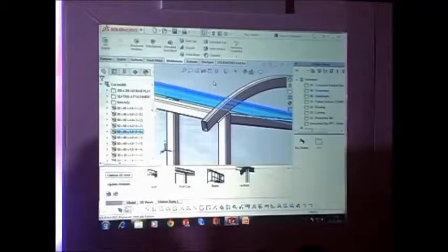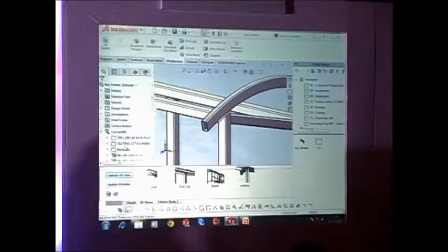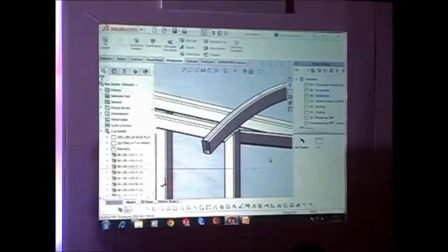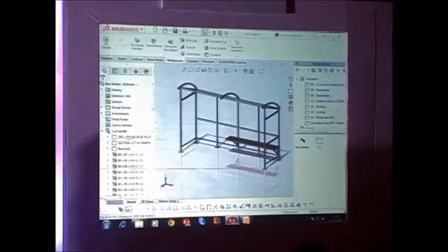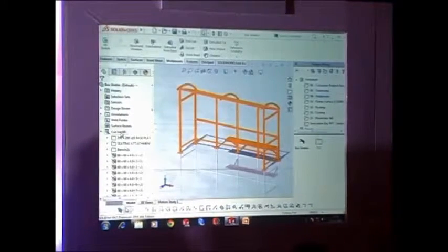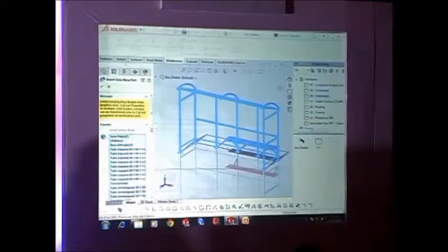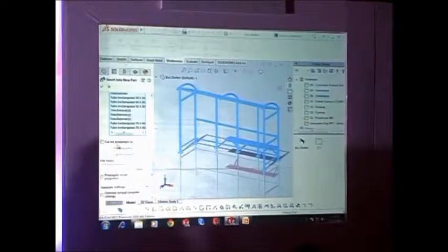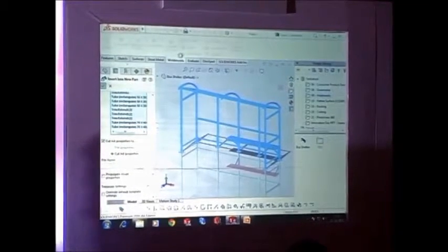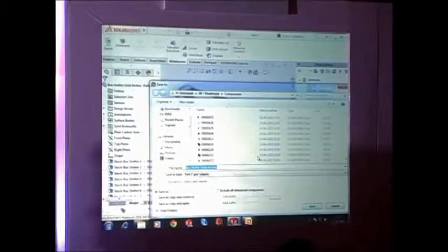So this is introduced in SolidWorks 2016. Many of the customer requirements are about creating a derived part to copy the structural member into a new part. By checking this option, we easily get a new part of an individual structural member.